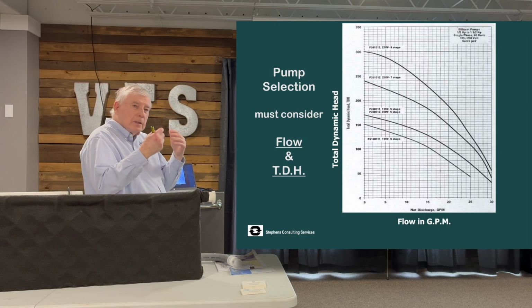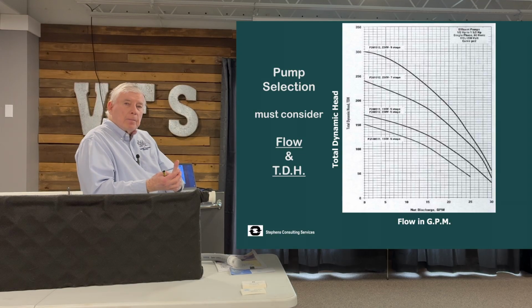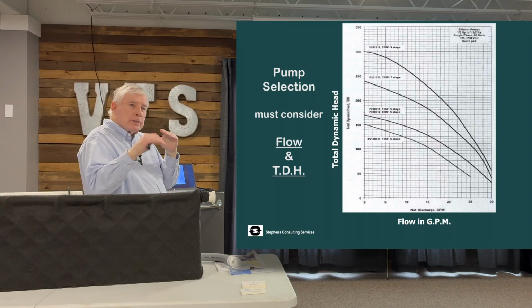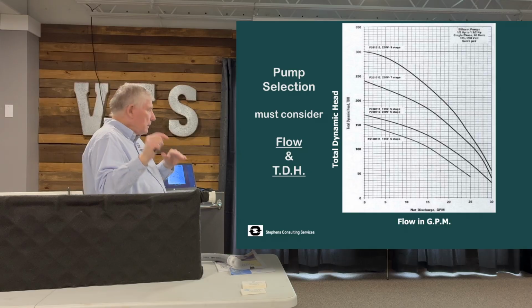You can't just say, I need a 50-gallon-a-minute pump. You need both: a 50-gallon-a-minute pump, and at what pressure does it have to discharge? So what's the head loss? TDH, total design head.